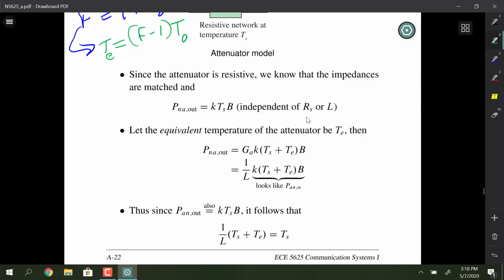Generally, you don't use attenuators in a receiver front end unless there's something really bizarre that you have to deal with, like a strong signal or something, because attenuators do something really bad, and we're going to see what that is in just a second. But another application of attenuators is as a padding mechanism to help match impedances, and I've used them for that before in one of my jobs, my first job actually. We would use attenuators, also referred to as pads, because you use an attenuator to pad two circuits so they don't interact with each other.